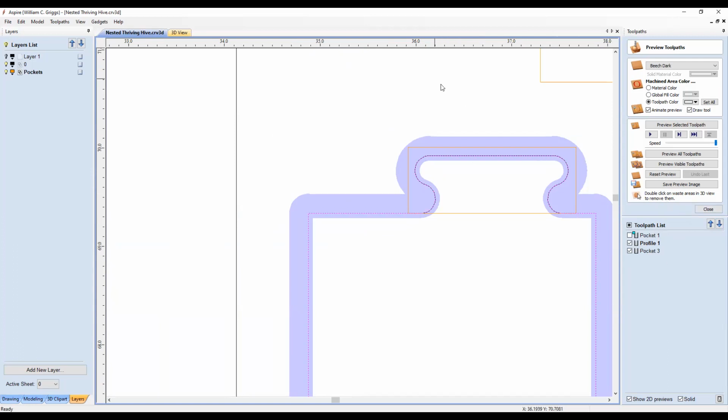Yeah, eCabinets does pretty much the same thing. When you set up a dado in eCabinets, you set up a fit tolerance and a depth tolerance, and it doesn't show it in the drawings. You can't take your tape measure or ruler and measure and see that 3 thousandths or 5 thousandths you added. It doesn't show up. But when it cuts it on the machine, it knows what to do.